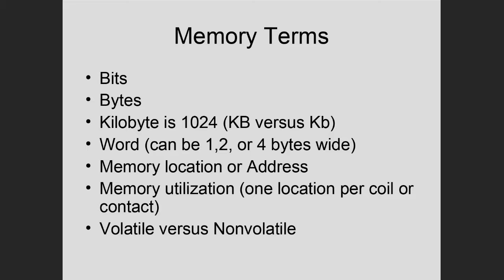So for us in here, a word is going to be 16 bits. And the reason is the screw terminals that we use to connect to the input module or output module on your simulation software: there are 16 of them. Remember, in digital, we start counting with 0. If I had the physical PLC in here right now and pointed to the input module, there's a door on it that I can open, and you will see 16 screws labeled 0 through 15, and above or below each screw, you'll see 16 LEDs.